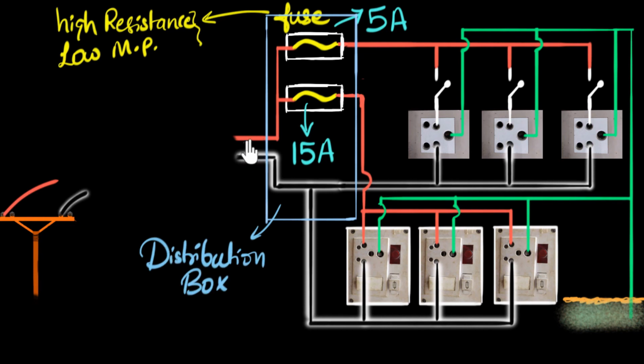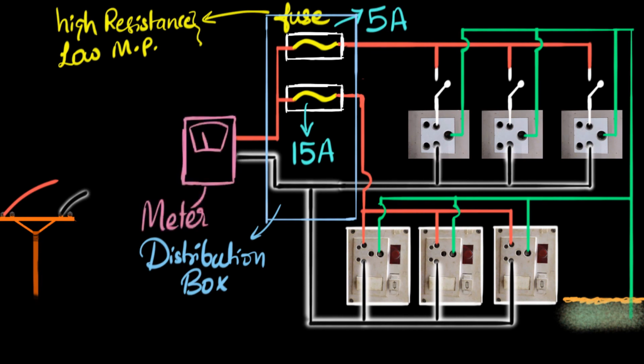And then this wire can now go out of your house and connect to that electric pole, but your electric company needs to bill you, right? They need to know how much electricity you're using. It's for that reason it doesn't directly go, it goes through an electric meter. Again, something you may have seen. The basic idea behind this meter, at least the old ones, is that there would be a disk, and depending upon how much current you're drawing, the disk will keep on rotating, and then they will just calculate the total number of rotations the disk has turned, and that's how they calculate how much electricity you've used. And so from there, the wires will get connected to the mains through another fuse.